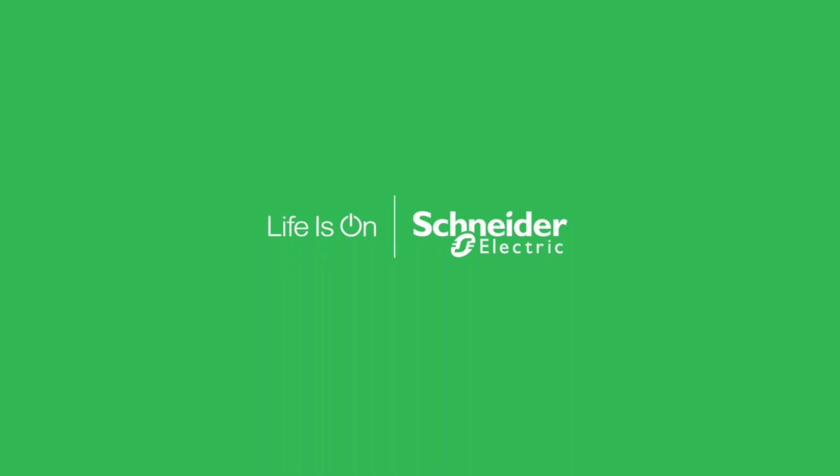Good question. So the room controller, you configure it on the configuration screen to tell it that it's pressure independent or pressure dependent. So it's all right there. It's not a separate firmware or anything. It actually says PI or PD, and you just select it. In a pressure dependent application, they don't use a differential pressure sensor to measure velocity out of the box. So there's no pressure transducer that's required for a pressure dependent application.